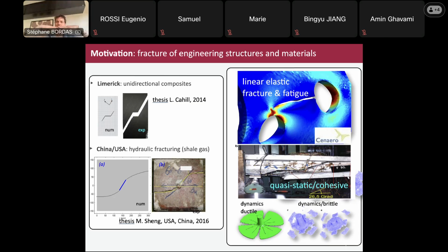And what happens if you have a concrete beam is that you bend it like this. If you see a screen, I'm trying to mimic the bending. So the bending means that at the bottom, you will have tension because everything that's at the bottom will be pulled from each other. You can imagine you take a ruler and you bend it like that. At the top, the fibers will compress together. At the bottom, they will extend.